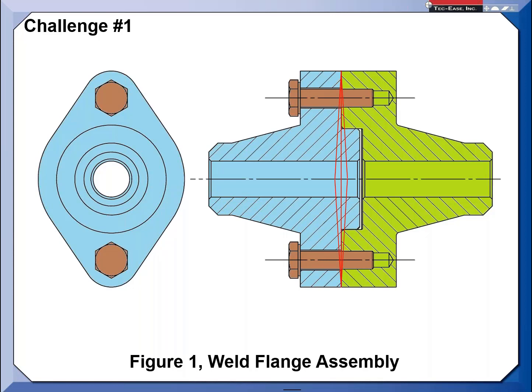It could go the other way, and you can have these stable, but again, you could have variation in the sealing surface. That's why in real mechanical design, there's a gasket in there that compensates for any of this variation. I just left that out and didn't make it part of this design.